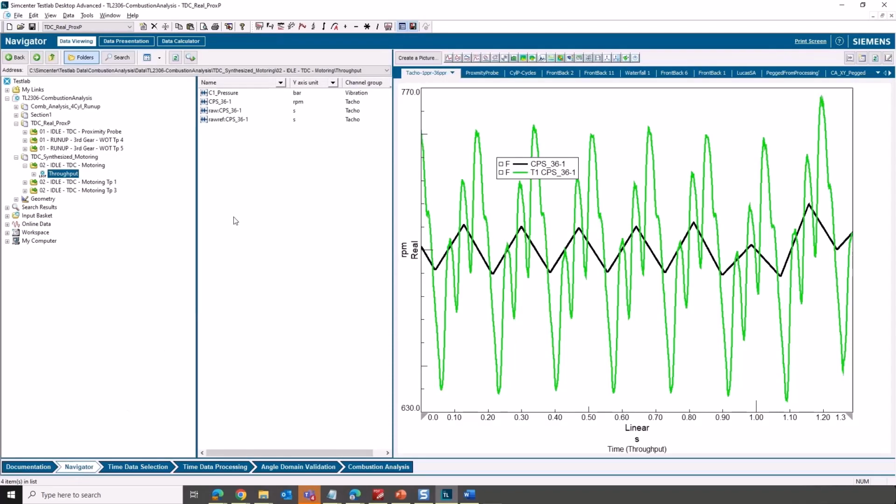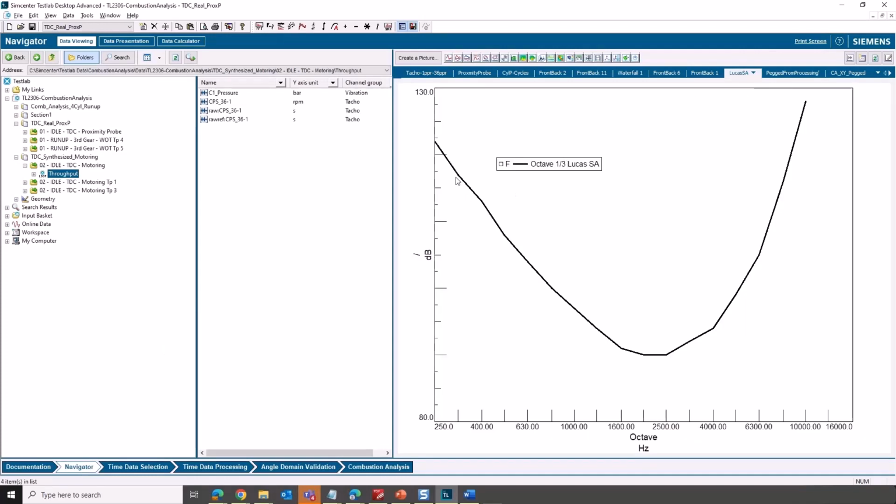Yes. Okay, so in this case, I have plotted that transfer function, and this is how it looks. It is defined in terms of octaves. The cylinder pressure is divided by this function here. Yeah, so low frequencies will be less, high frequencies will be less in the end, kind of like the A weighting curve of the human ear. Right, low frequencies will be attenuated more. Is that what you mean, Pete? Low will be attenuated and high will be attenuated. That's correct, yes, compared to the mid frequency range. Right, exactly. So, the inverse of the A weighting curve, I should say. Right. Yeah.